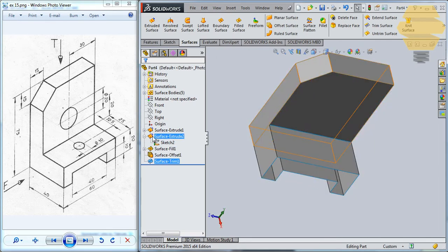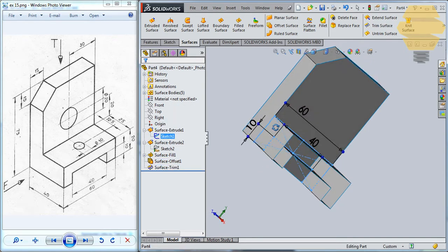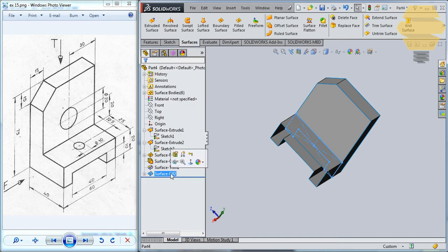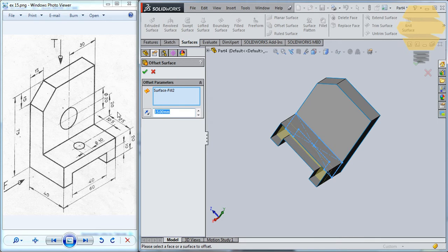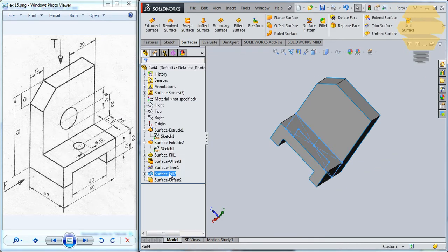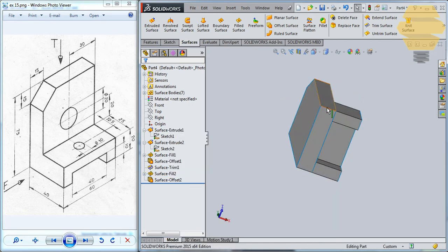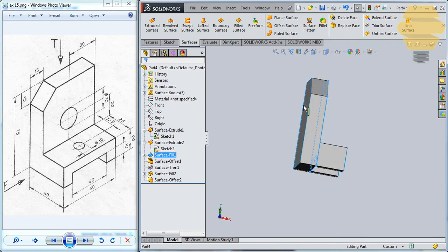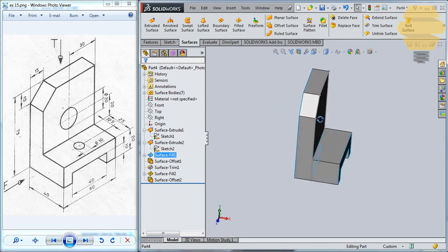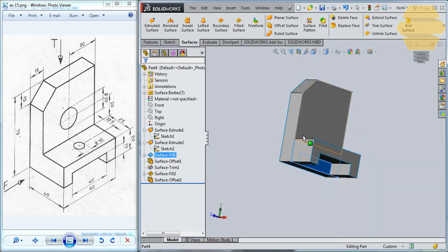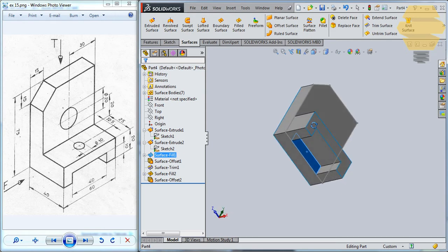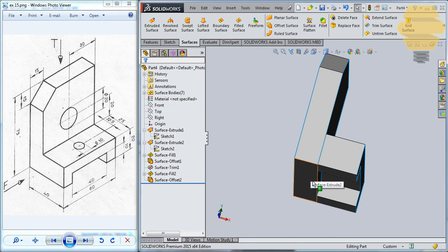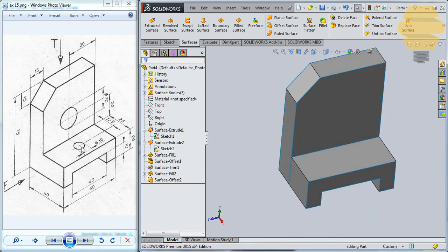Now what we can do is firstly create the surface, right? You can take that sketch here. That sketch is over there, so I'll go for fill surface, fill that, and offset it up to 25, tick mark, and take that fill and hide it. Now that surface doesn't exist there. And if at all we had to create this throughout, we can just create a rectangle here and extrude it and then trim this portion off, just the way we did over here.